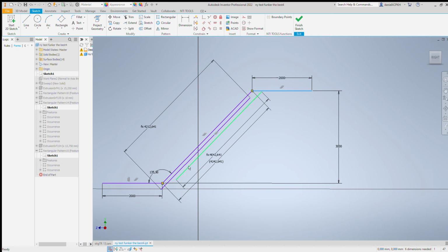Look, this hypotenuse, I call this a driven dimension. What drives it is this height and this angle. First you have to do this, because obviously you can't call it from here, since it's a driven dimension. You have to go here and find it here, because you know how much it is. Just write it here, call it hypotenuse or something. Now it's your driven dimension.